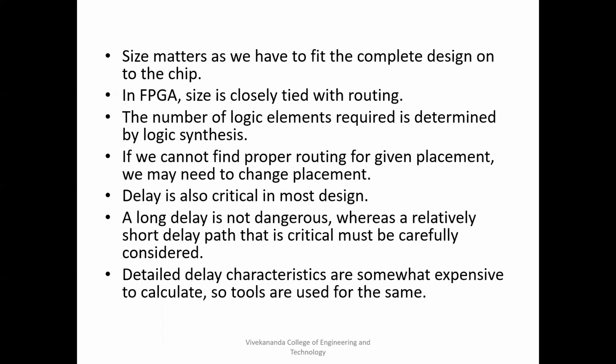As I said, whenever we talk about placement and routing, the size comes into picture. You can place it haphazardly, but the size will increase. So in a given size, how effectively you can place and how well you can route them so that the delay will be less and the power dissipation will be less is very important. You shouldn't connect such that you get a very long delay.